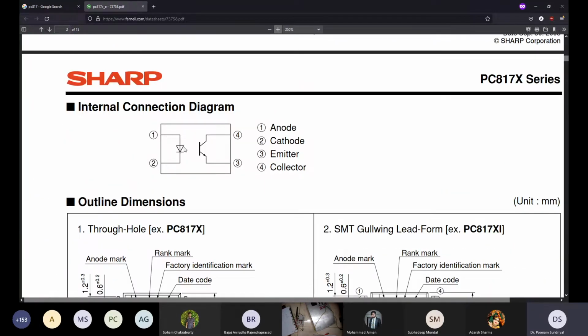So this is the light emitting diode. It only gets signals from the microcontroller, meaning it's going to have something which is low voltage, low ampere. All the switching that's going to go on is between the collector and emitter, between 4 and 3. So you will say that whenever I'm driving higher voltages across 4 and 3, there's a chance that this collector emitter path can get damaged, right? The only thing that can get damaged is 4 to 3.